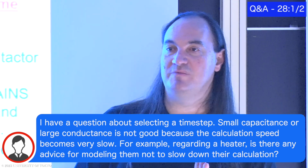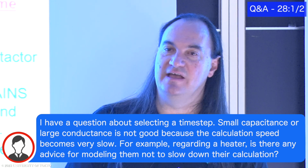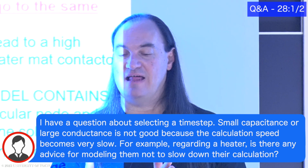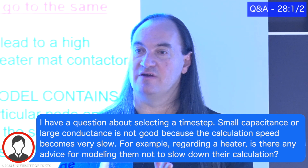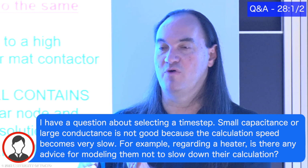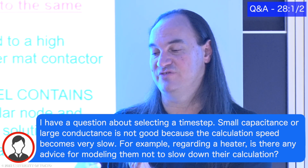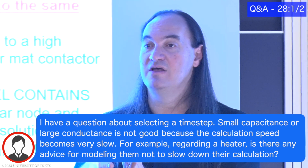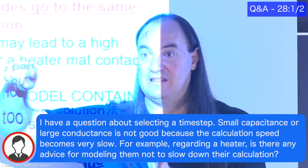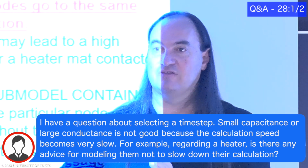So if you wish to get heaters to behave better, one of the things that I have played with is, after a certain number of loops, start tallying up how much heat a heater has been applying. So let's say I let it go for 50 loops, and then for the next 50 loops, I'm going to sum up the heater power. And then I'm going to divide that sum by 50 loops and apply it as a constant value. So now my heater that had been oscillating like this, I'm going to average and let it stay at a flat line. And now without this oscillatory behavior, that flat line gets to convergence better.